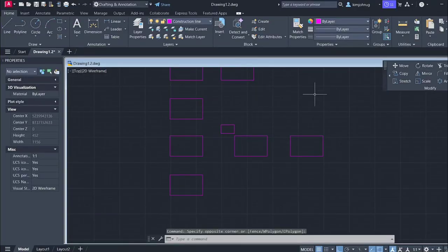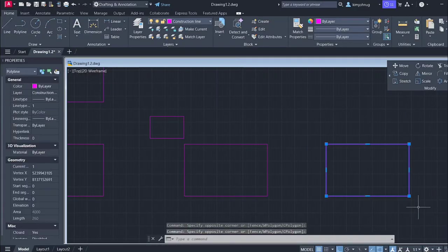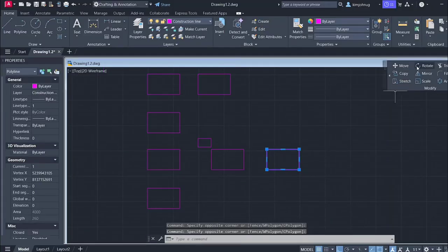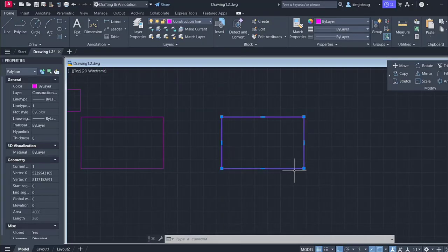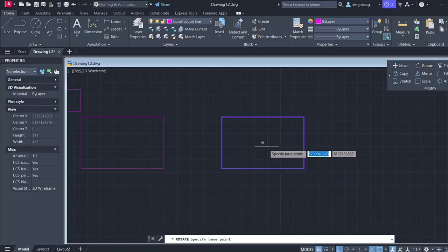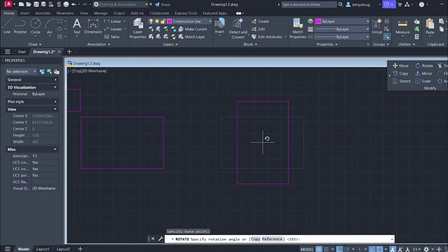So let's move on to rotate. To rotate simply means to change the angle of the object. For example, let me say I want to rotate it using the center. With this auto mode on, you realize it rotates only at 90s. If that's your plan, it's fine, but that's not mine.